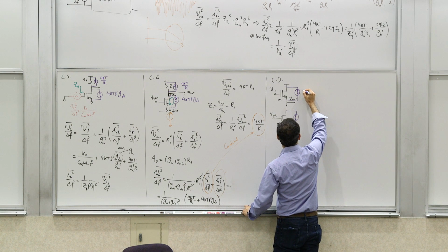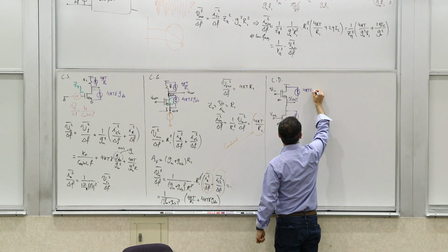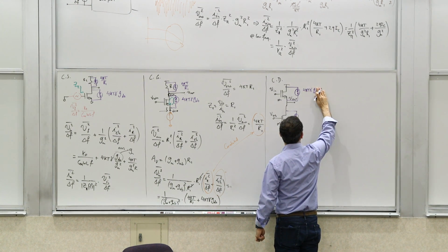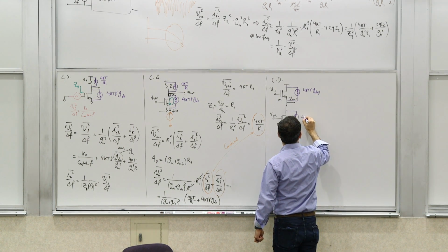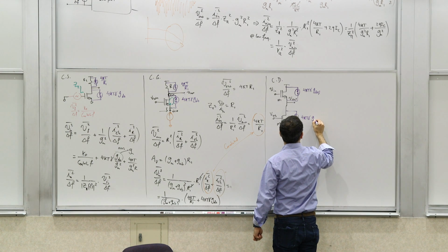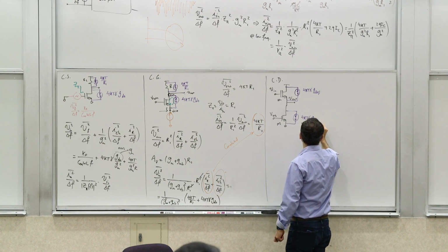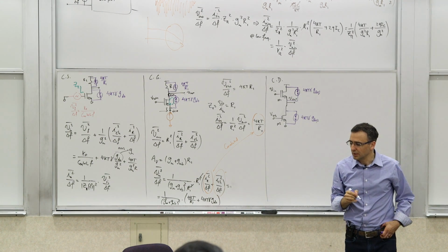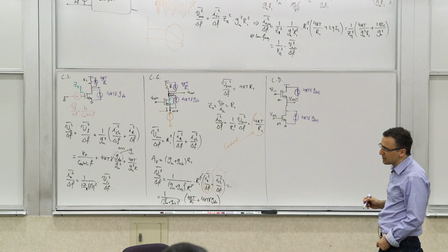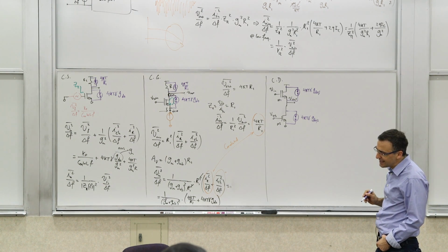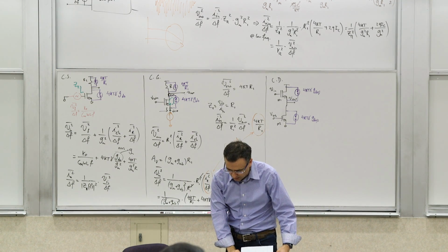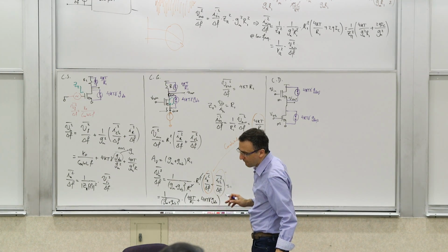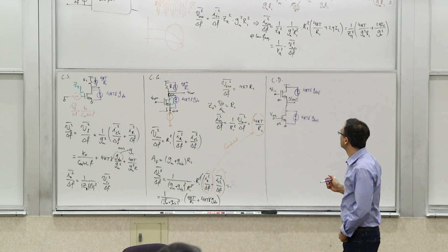So this noise source is 4kTγgd01, and this is 4kTγgd02. In general, the gammas may also be even different. And then the question becomes, what is the gain of the stage? How do we deal with that? What is the gain of this amplifier?